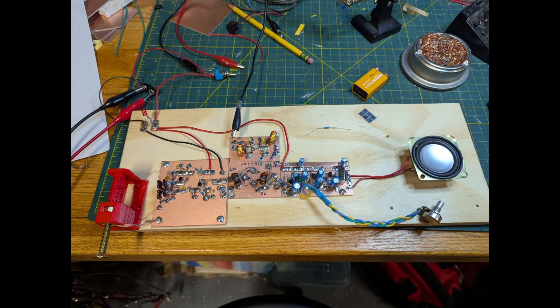One thing I would advise you is to listen at various times of the day over a couple of days before you start making any changes to the receiver. Even fussing with the audio stage, just listen. Listen in the morning, listen during the day, listen during the evening. 40 meters is a very finicky band, and sometimes the signals are very strong, and sometimes they're not so strong. And sometimes you think you need more amplification, and sometimes you think you need an RF attenuator. So listen before you make any changes, and it's one of the best pieces of advice I can give you.